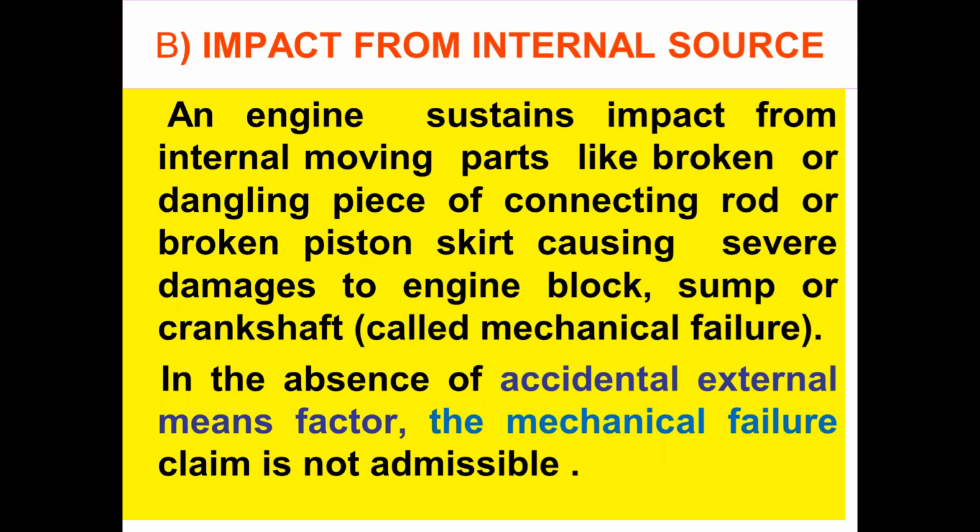Impact from internal source. An engine sustains impact from internal moving parts like a broken or dangling piece of connecting rod or broken piston skirt causing severe damages to engine block, sump or crankshaft, called mechanical failure. In the absence of accidental external means factor, the mechanical failure claim is not admissible.